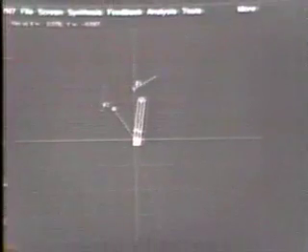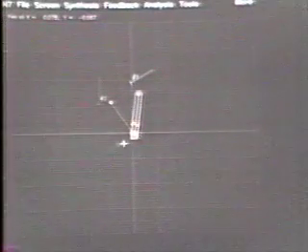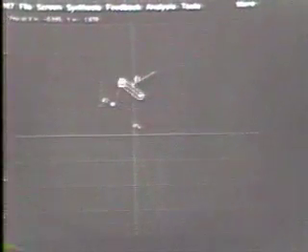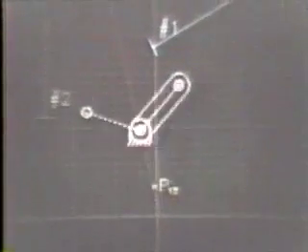At this point, the designer is starting on a new problem. Rather than use a picture to represent the moving body, the designer is simply using the T-shaped plane icon. The plane icon is shown in both the number 1 and the number 2 positions. The designer just put out a moving pivot and has grabbed a fixed pivot and is sliding it back and forth on the straight line locus of possible fixed pivots for this 2-position problem.